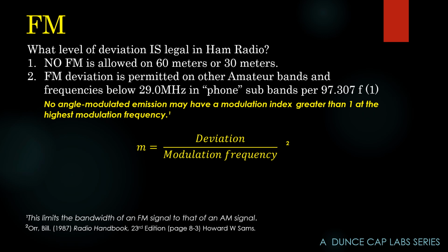So FM is actually legal on HF. It's just you can't do much more than, oddly enough, the new standard, remember, in land mobile radio is 2.5 kilohertz deviation. Essentially, that's almost what we're limited to. Now, FM on HF with the noise and other signals, FM just doesn't work that well on HF anyway. So we're not losing anything by being limited. Yes, FM is a lot of fun on 10 meters, but FM is a little bit limited in that it requires a much better signal to noise ratio than single sideband does.